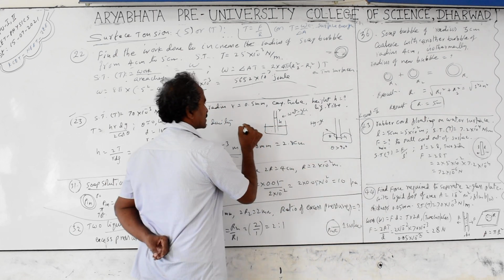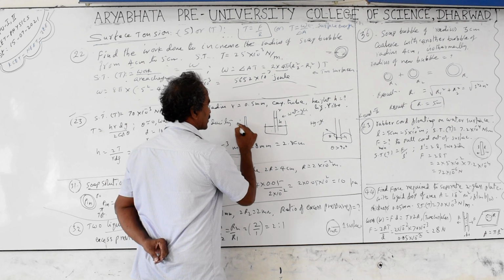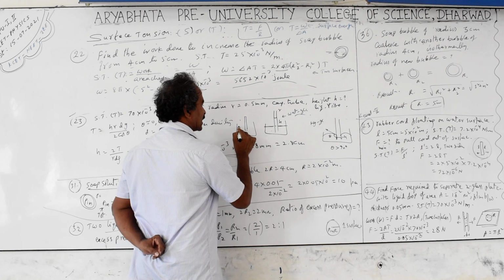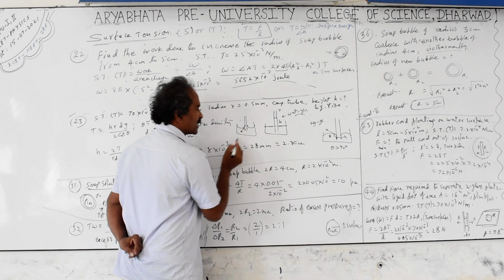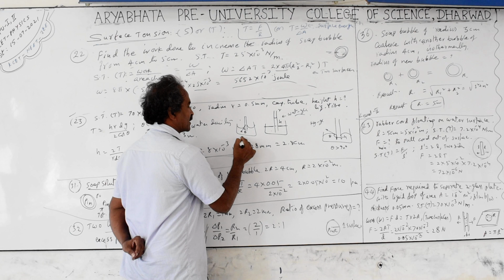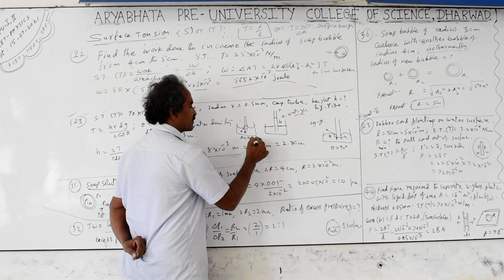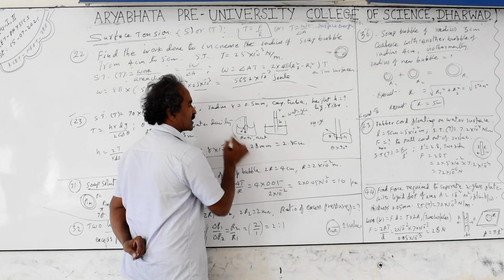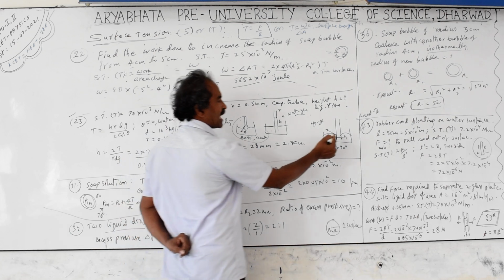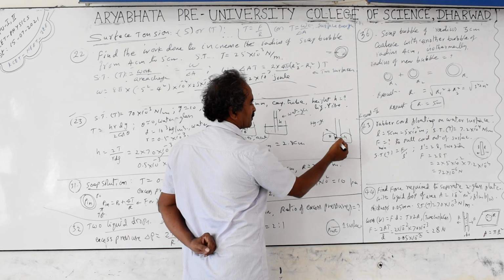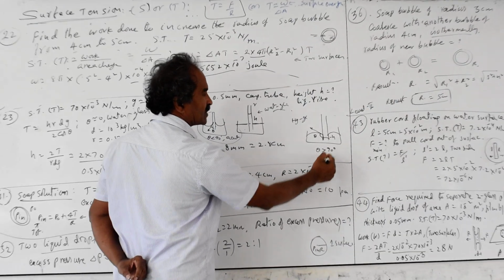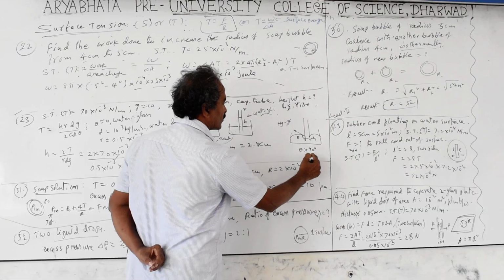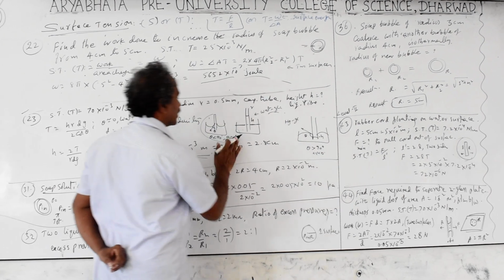If you insert the same glass rod into water, the liquid level will rise, and the theta is less than 90 degrees, called an acute angle. For glass and mercury, it is an obtuse angle, more than 90 degrees, as it does not stick to the glass. This value is approximately 140 degrees for mercury and glass.